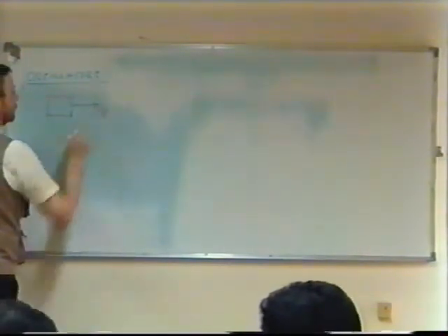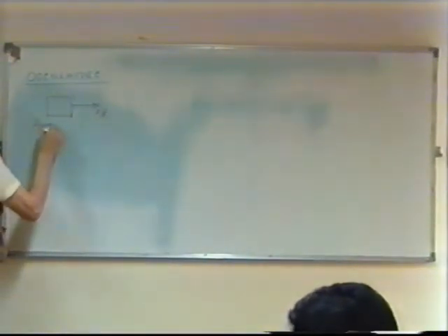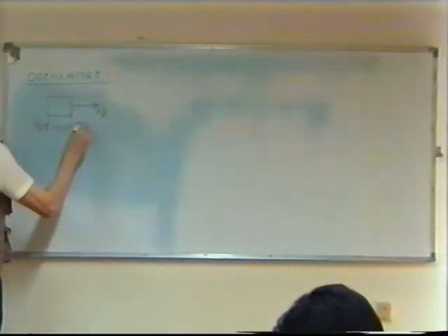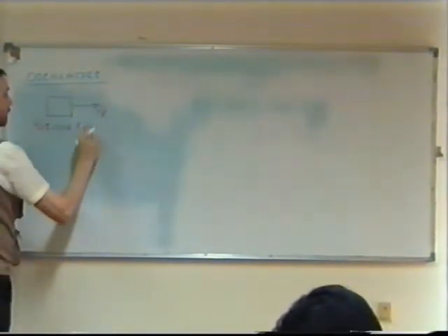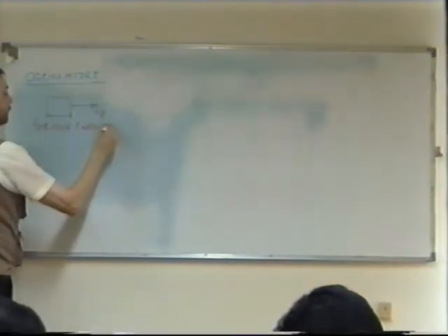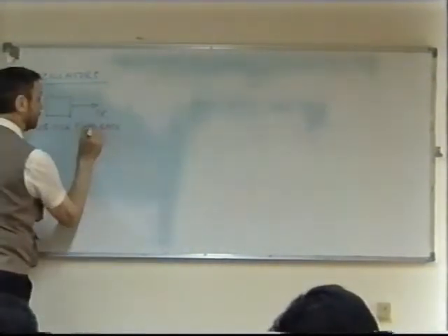As you know, an oscillator has an output, but unlike an amplifier, it doesn't need an input. How do we achieve this? If you remember when we were speaking about feedback. Yes, if we use enough positive feedback, and it doesn't have to be very much, we get this output. So we need positive feedback. That's part of the condition for an oscillator to work. Feedback. So whatever circuit you see in a diagram, you must look for your positive feedback path to see what's happening.